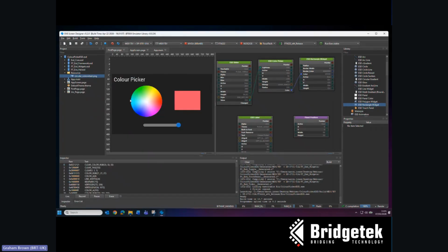one of the things we can do also with ESD is to check the resultant display list commands. These are the lower level EVE commands used to generate the screen. And if we're happy with all of this, we might want to port the project onto our MCU. So one of the things we might want to do is rearrange where the files are on our MCU. So if we select our color picker image, we can move this from a file to program memory,